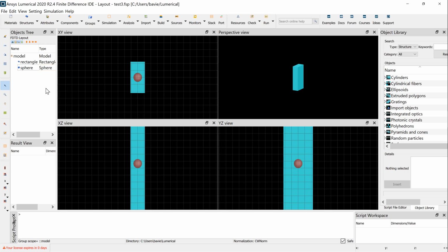There are also other ways to define material overlap. In fact, the proper way to do it is to define an index of the material. It's not a refractive index, it is a computational index introduced to prioritize materials in the domain. The material with the highest priority is inserted inside the material with the lowest priority.